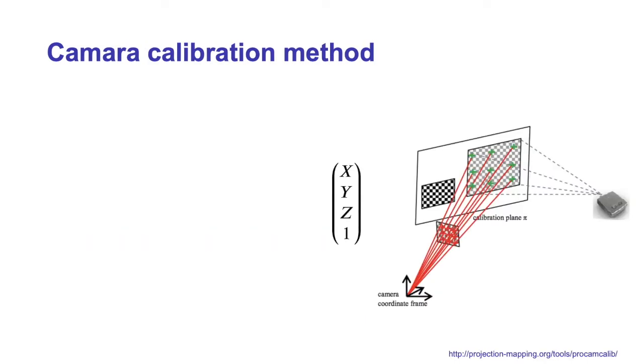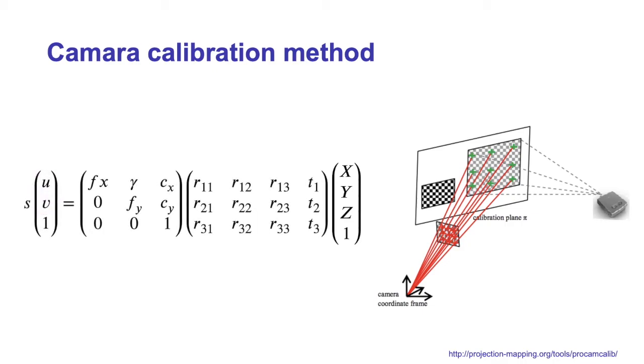Camera calibration methods use special calibration patterns to estimate the parameters necessary to determine the scaling factors to be used on the images. After obtaining the camera parameters, the world coordinates of any image point can be reconstructed from its image coordinates. The most frequently adopted pinhole model for camera calibration relates the 3D world coordinates x, y, and z of a calibration target point with its corresponding location u and v in the image plane using the perspective projection